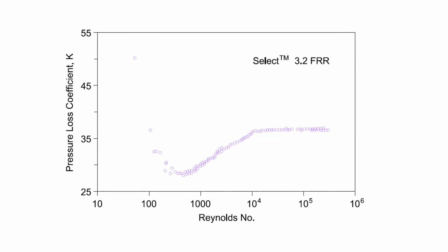Look at this curve. It's very relevant here to use the log of Reynolds, because between this number and this scale, over these orders of magnitude in the log scale, it's very linear, and after this number it's very steady state, and there is a change here. That's why we use log, and it's consistent even for the pressure loss coefficient to use log. But the inverse is an idea that we brought in. And why do we use the inverse? Because as you see here,